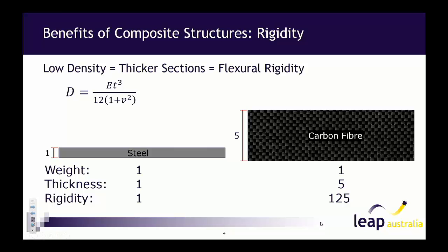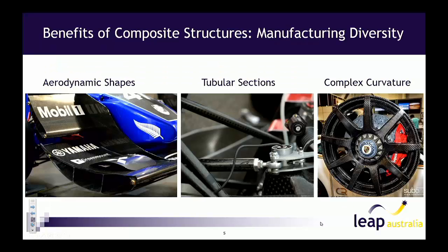So integrating these into your structures, you're going to have a very rigid chassis, very rigid suspension linkages, very rigid aerodynamic surfaces, all good things that you want in a vehicle. A couple of the other benefits: the first one, they obviously lend themselves quite well to being shaped into nice aerodynamic profiles. You can see manufacturing things like inbuilt stiffeners, something that would be quite advantageous to use in composites.